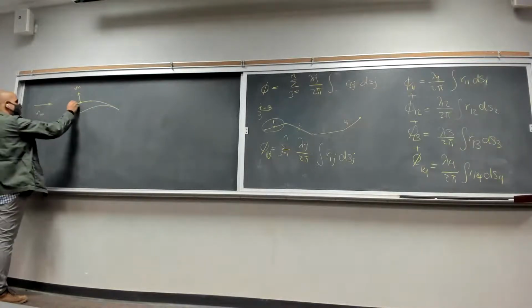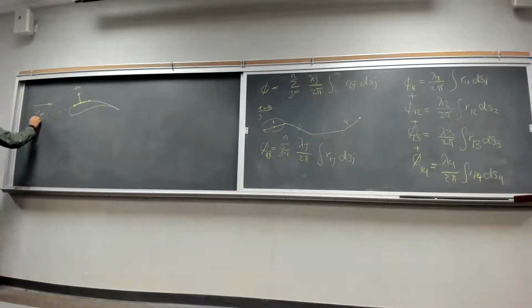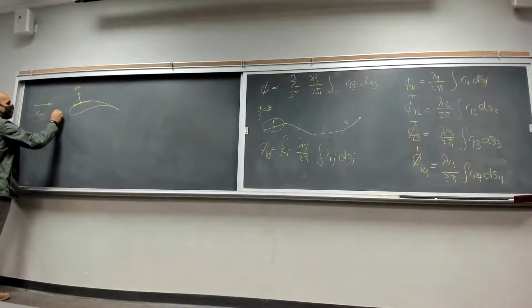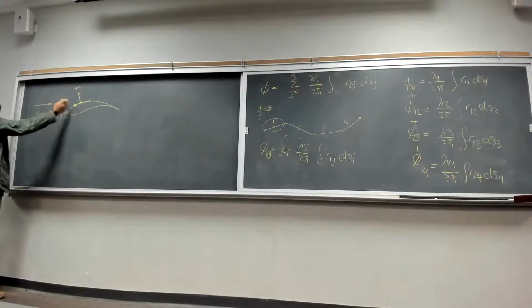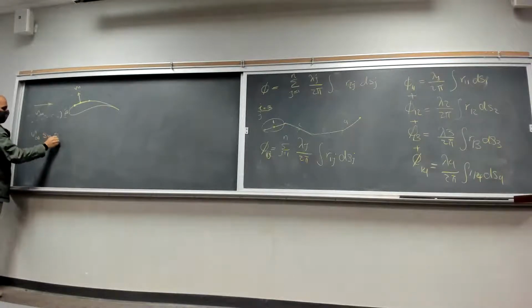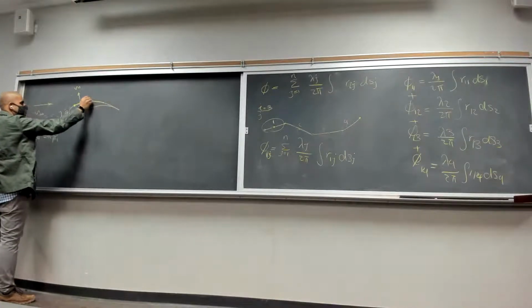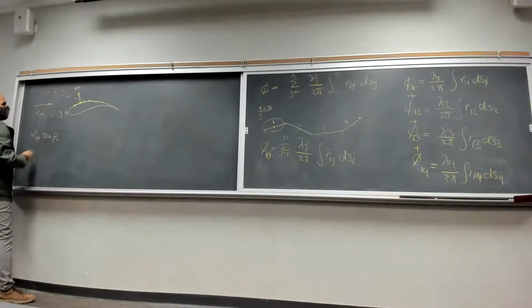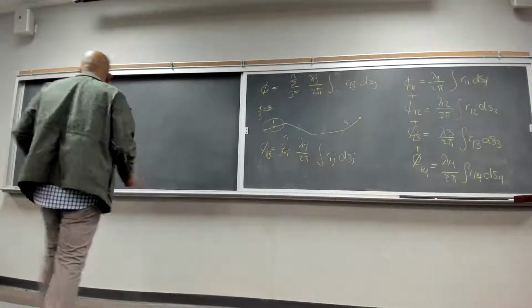Let's say you have these panels here, and the angle your flow direction makes with a panel is called angle beta. So the normal component of the free stream velocity is going to be V infinity sine of beta. This angle is also going to change for different panels. The angle this panel makes is going to be different than the angle this one makes with your free stream flow. Sorry, this is cosine of beta.